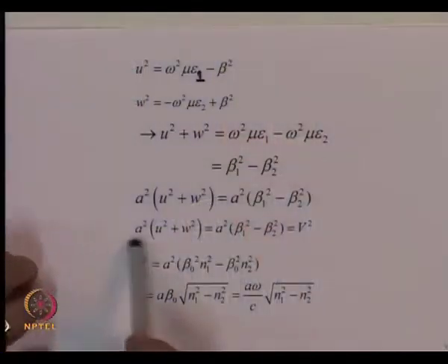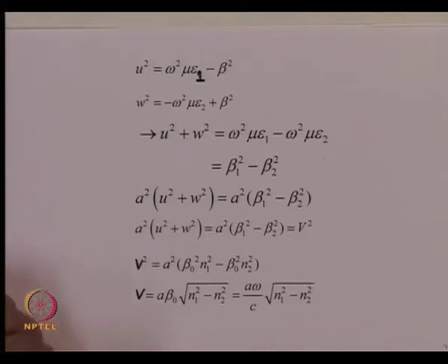But we have seen that just the difference in refractive index does not completely characterize the fiber propagation, because depending upon the size of the core, different numbers of modes can propagate in the fiber. That means a parameter defined only on the basis of refractive indices doesn't completely describe the propagation characteristics. So now we find this parameter is a more complete parameter for describing the fiber.